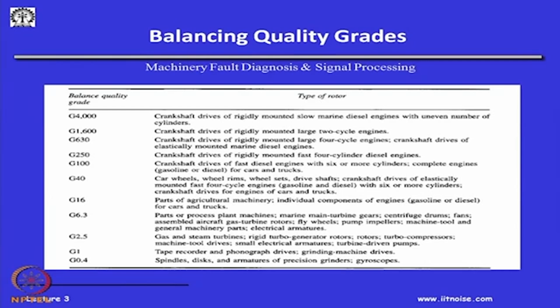Now, the question is, with this brief understanding of unbalance, what effects can it have on systems? Many machinery components actually start failing because of unbalance. Unbalance gives rise to excessive forces at the supports, so the supports, the bearings, will get damaged. So, we may be alarmed because of a bearing failure, but the initial problem could be something else, not the bearing.